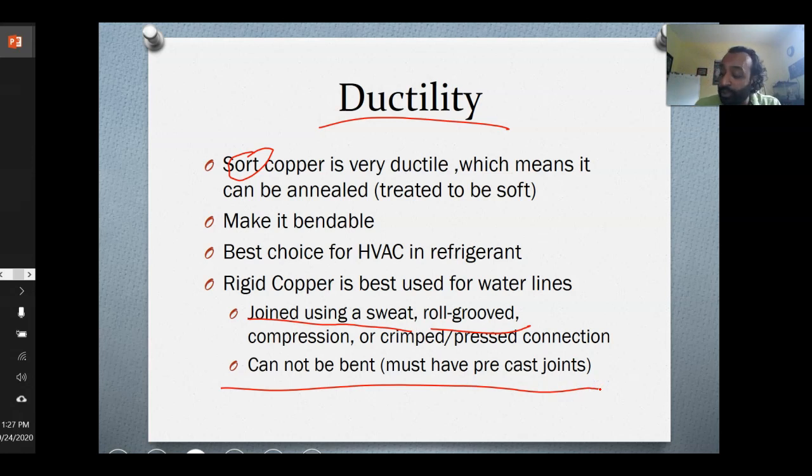When you purchase the copper, are you going to need to bend it or not? If not, you might want to buy the correct fittings. Sometimes even with bendable copper, when it's thick and large, it's really hard to make the correct bend.